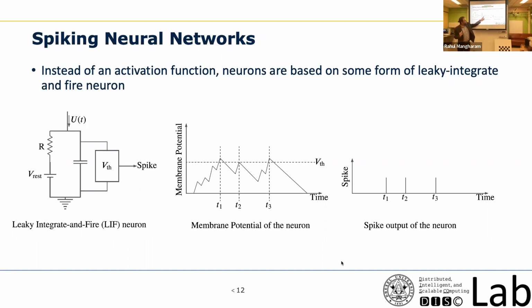So it's a capacitive behavior. If you don't do anything, this capacitor will lose charge over time. Is VTH a resistor? No, this is a threshold voltage, and I will come to that. You have a current flowing charge into this capacitor. If the current is not there, the capacitor will discharge, right?